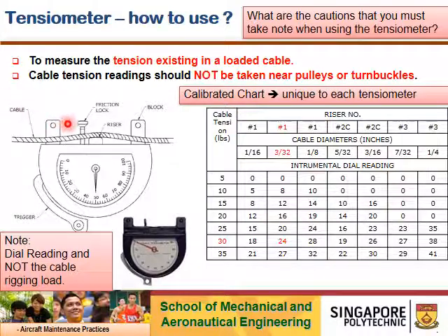I think this is repeating. Make sure that there's a chart that goes with each individual tensionometer, so make sure that you refer to the right box. In our practical, we have put the cable tensionometer in a box, and the box provided will give you that chart. Make sure that you use the right tensionometer with the right chart.